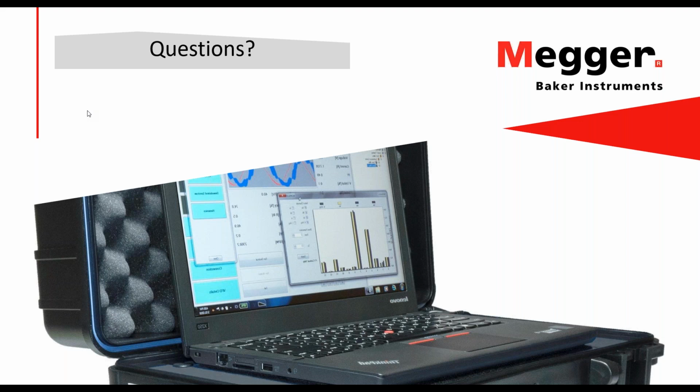So if we knew the lead resistance of the application under test, then we can be more accurate at the voltage drop that occurs from where we're sensing voltage to what the motor actually is seeing. So again, we can be more accurate if you give us that lead resistance, and if you give us stator resistance, which you can find from your static testing. You can give us stator resistance there.